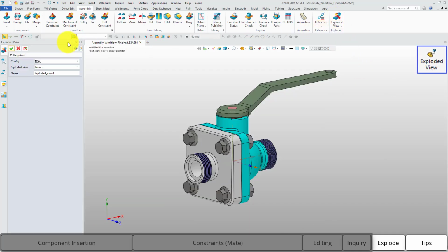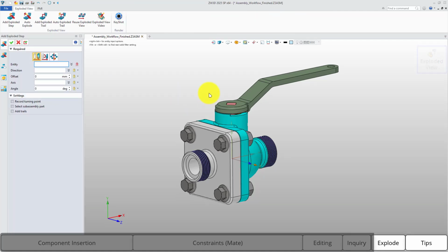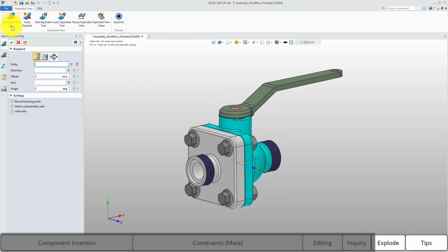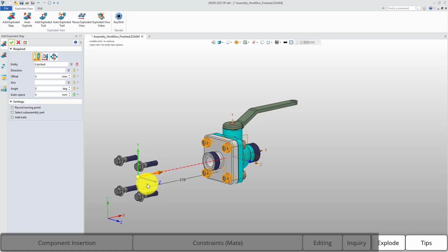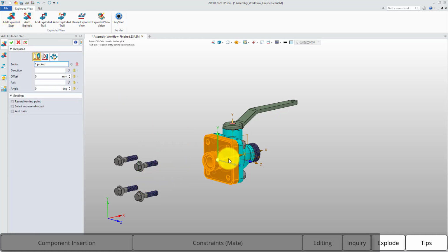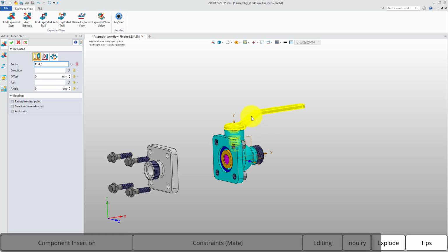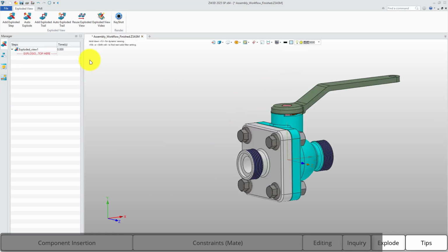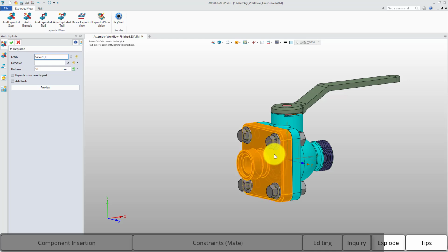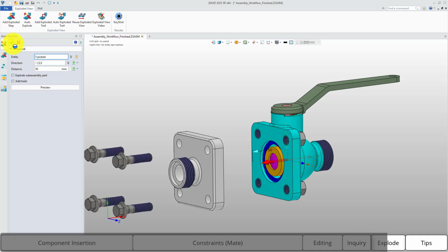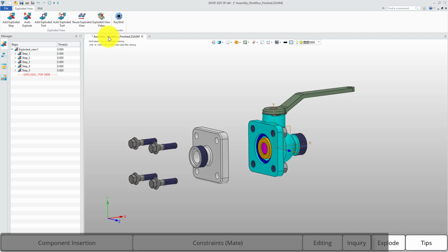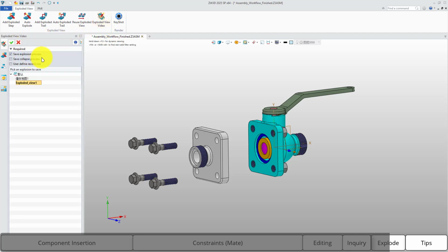Finally, let's talk about Explode View. Exploded view can be manual or automatic. Manual explode view needs manually selecting components and setting them to the corresponding position, adding each explode step as you go. Auto explode involves selecting the object to explode, choosing a direction, and setting a distance, and the animation will be generated automatically according to the parameters.